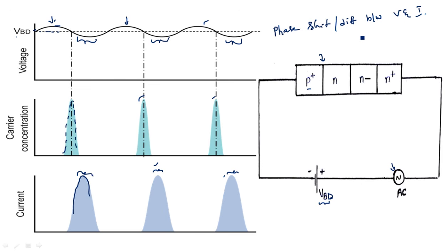As voltage is positive, current is negative, which means the diode is operated with negative resistance characteristics, hence it is acting as a sourcing device. This is the operation, construction and working of this IMPATT diode.